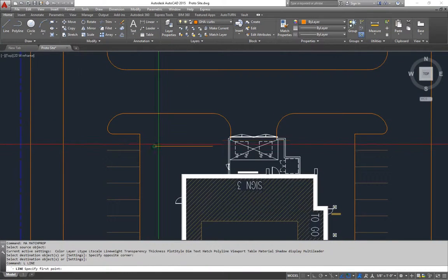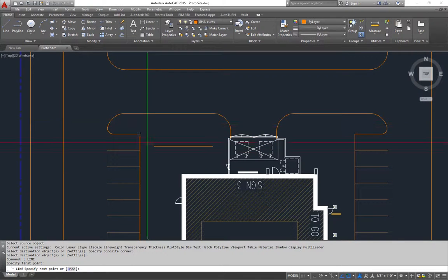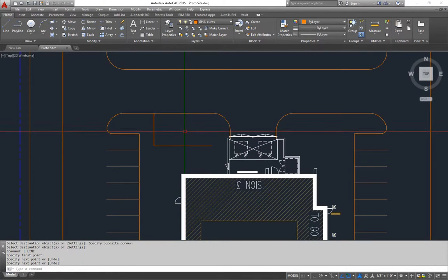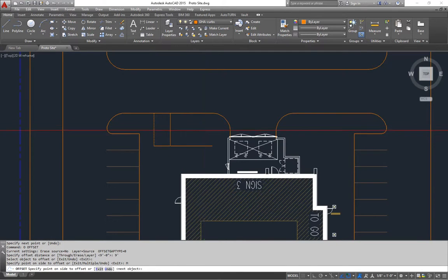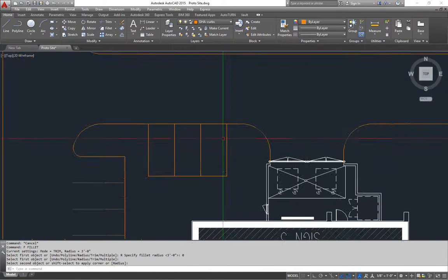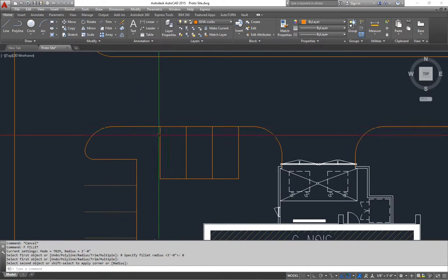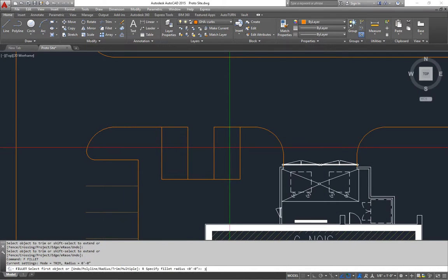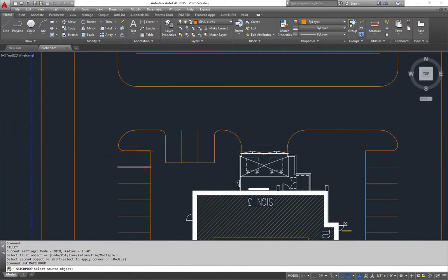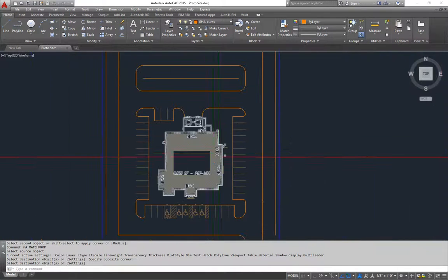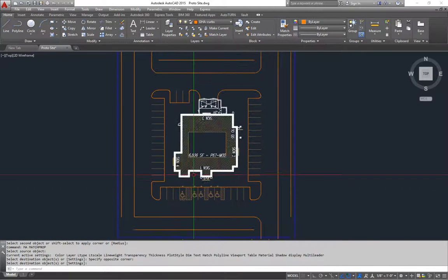Alright, now we move on to the back. Again, starting closest here so that we maintain this distance. Perpendicular. Offset 9 feet. Multiple. Yeah, we're only going to get about 3 spaces there. So I'm going to set my fillet radius to 0 and hit that. Now here, if I fillet this at 36, I'm going to lose this line over here. So before I do that, I want to trim one of these out. That way I can fillet it on both sides. So fillet radius 36. There and there, and then match there. So there's all the spaces on the stripes layer.